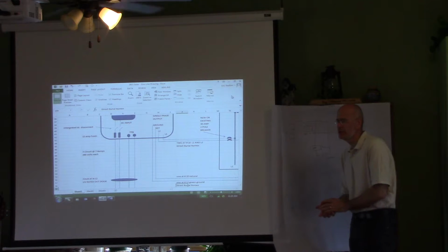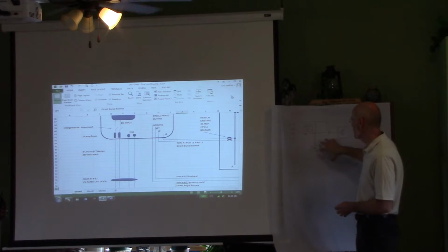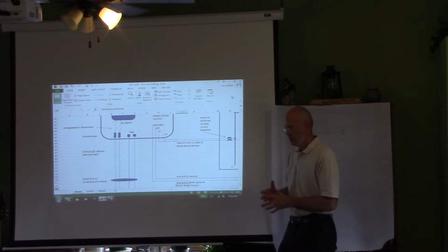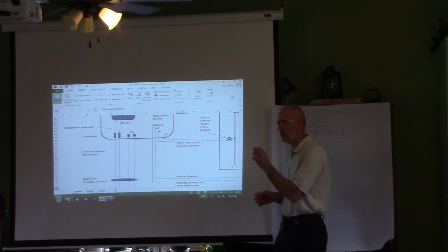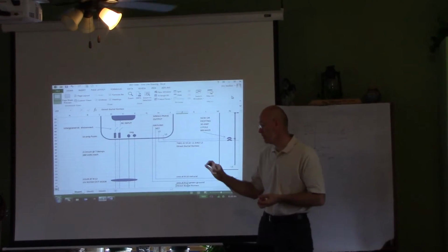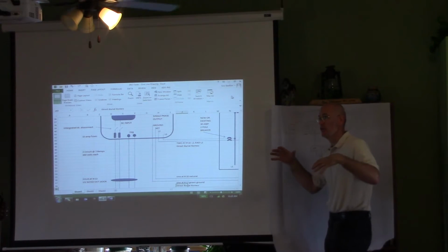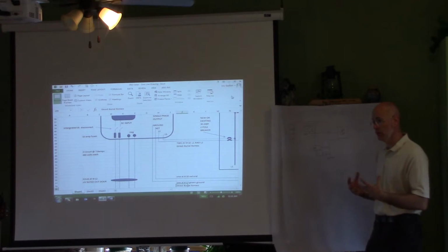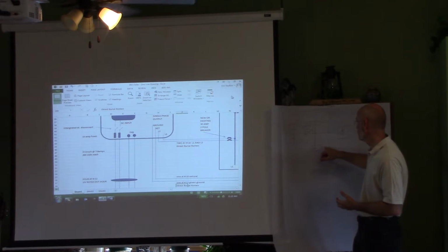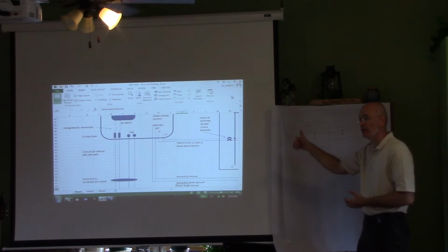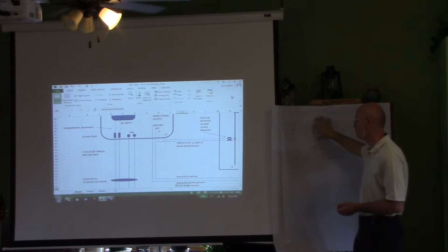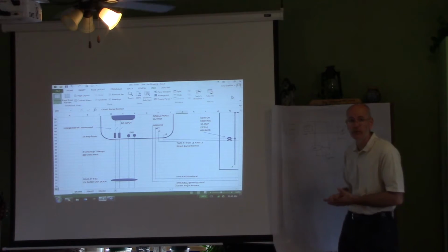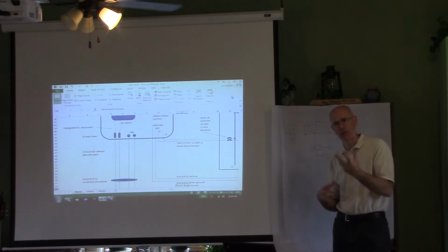It depends on your charge controller, but usually there's another heavy wire. And because you're dealing with a lower voltage in your battery, you're dealing with 24 or 12 volt batteries typically, maybe sometimes 48, the wire size goes from a little skinny number 12 up to a 300 MCM. I mean, literally the cable can be that big. Because you reduce the voltage, to get the same power, you've got to increase the amperage. And since batteries are generally lower voltage, that's a real heavy wire. It's the size of my thumb, at least, to go from the battery up to this off-grid inverter. But then out of the inverter, you're back down to your standard number 10 or 12 wire over to your load bank.